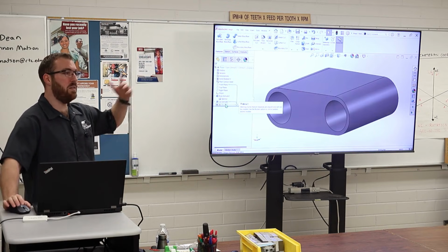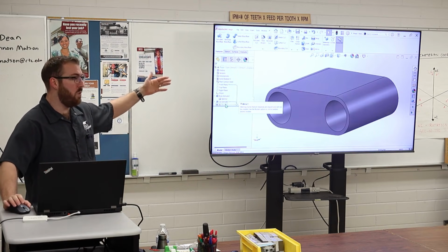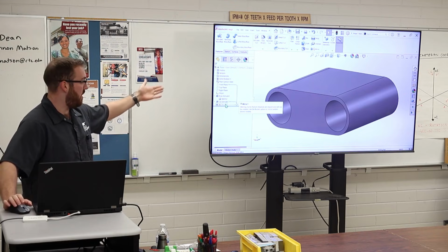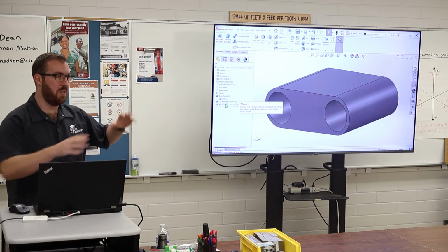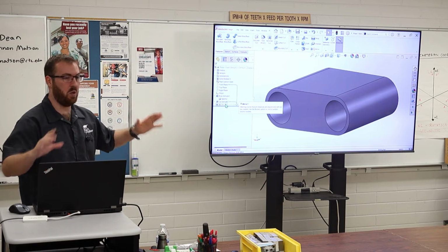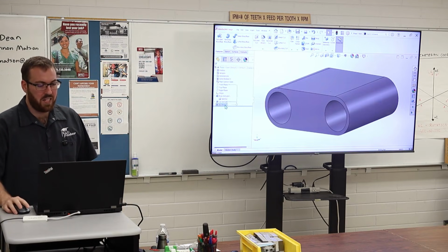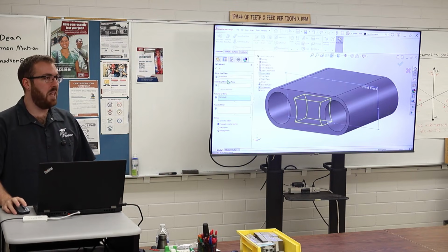But you could always, if you needed to, use the same sketch, create another feature on this face, right? But they wouldn't be linked, right? This could be the first sign of panic. You see the yellow or the red show up and it's over, right? This actually comes down to a pretty common error that we see a lot. It's the geometry pattern checkbox.